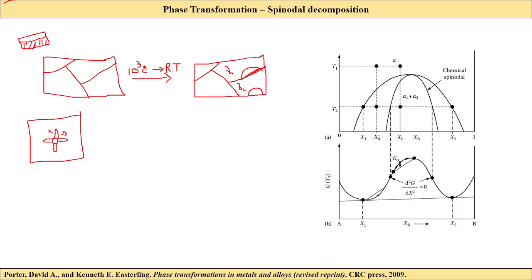A new grain is formed on the interface between gamma 1 and gamma 2, right? So there is already a surface here, and that is a grain boundary. What is the difference between gamma 1 and gamma 2 grains of the same phase? It is nothing but the planar orientation, how the atomic planes are oriented in a specific direction. For example, in gamma 1 we may have 111 planes facing this direction. In gamma 2 you might have a slightly different direction.